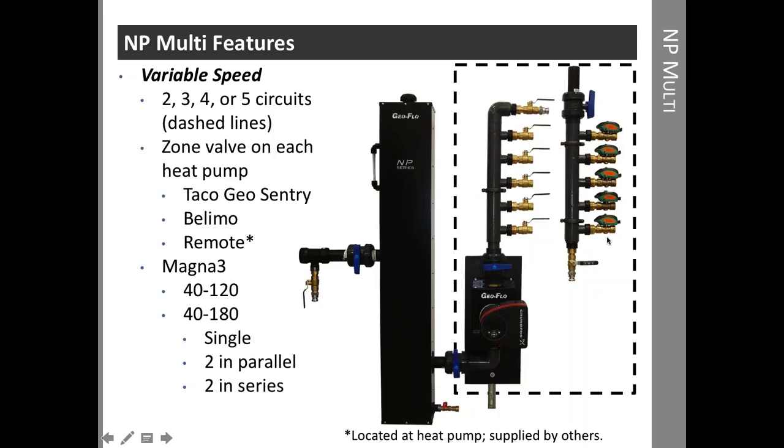Finally, if you want to have a remote valve, maybe you want the zone valve at the heat pump, then it could be terminated with just a ball valve instead of a zone valve here, and you can then install the zone valve at the heat pump.